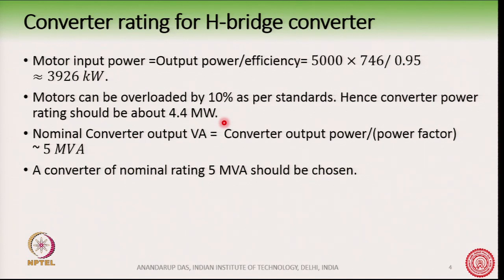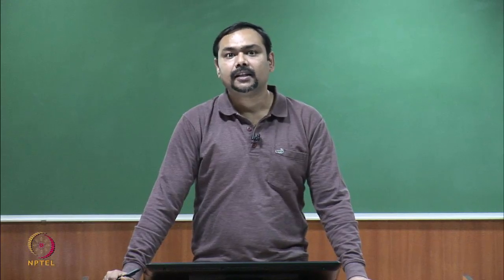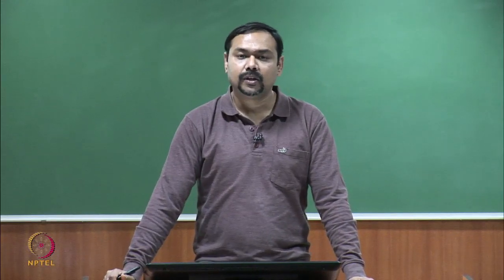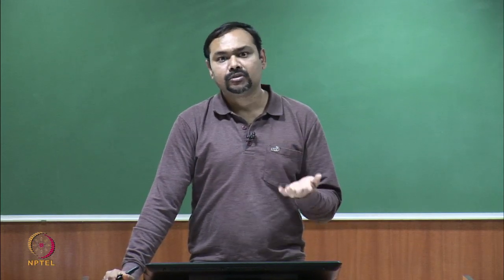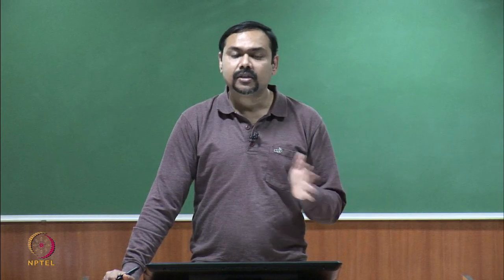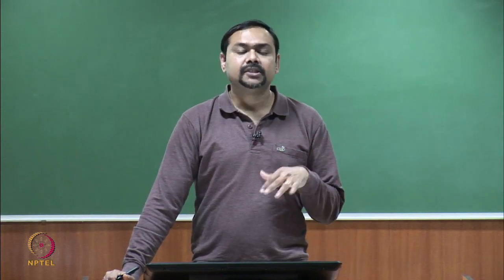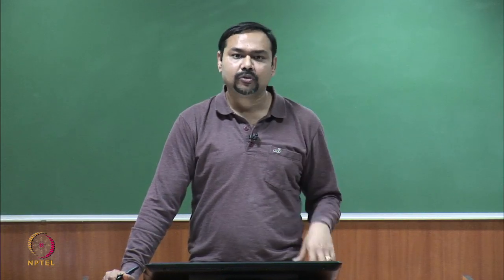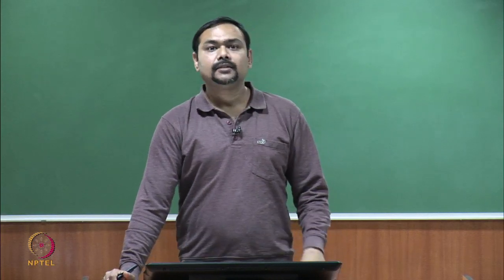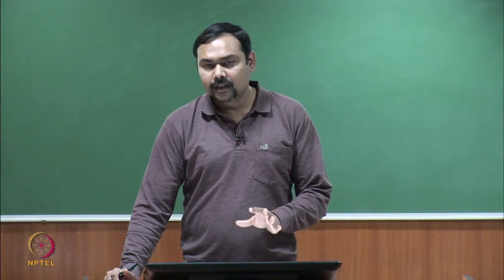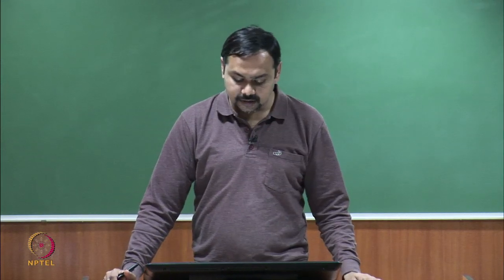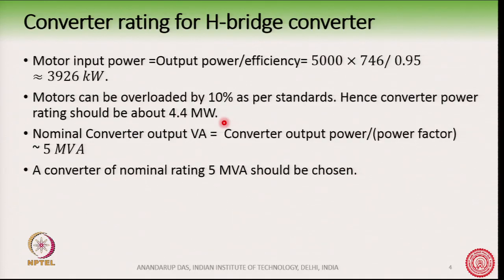When you say overload, another question that may come up is, for how much duration of overload? Is this 10% overload for 1 minute, or is this 10% overload for continuous operation? Generally it is not continuous, it is a short term overload rating. This will vary from application to application, but we are not going into so much detail of the direct application, and we are doing a simplistic analysis here.